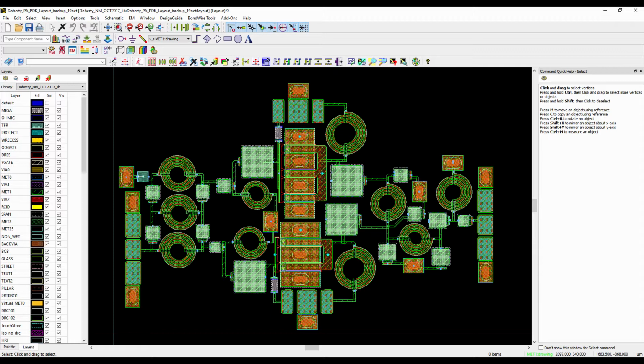The drain voltage is very high compared to the CMOS processes, because CMOS devices have very low breakdown voltage, whereas GaN devices or GaN HEMT transistors have higher breakdown voltage, and the higher VDD means usually higher power, right?